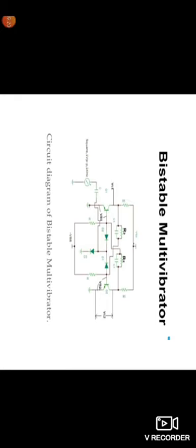Q2 in the on state means the collector potential decreases across transistor Q2, and that potential is connected to the base of transistor Q1, so transistor Q1 will move into the off state. The collector of transistor Q1 is at high potential, and that high potential is connected to the base of transistor Q2. Here is the total potential divider action of R1 and R2.